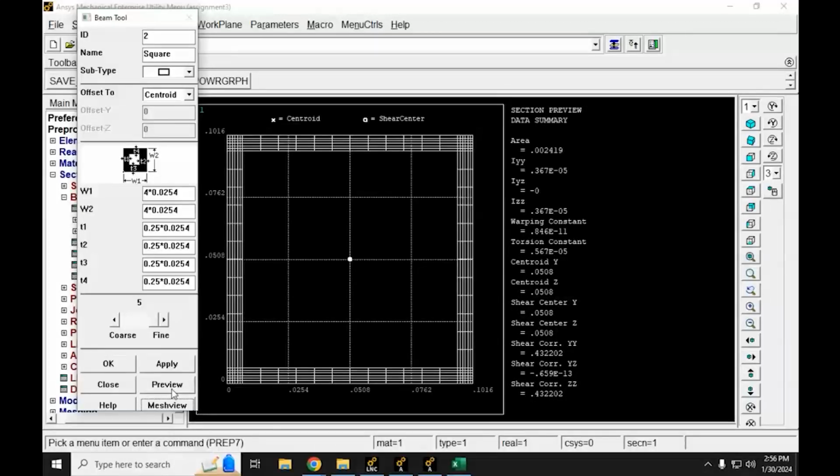The fineness of this mesh really doesn't matter. But if you ever had a scenario where you go past the yield point and start to plastically deform the object, you can figure out where the yield surface is. It's going to yield first at the outermost fibers, so it'll yield most at the outermost fibers, and then the yield surface is going to go down. You can figure out where that is if you put enough mesh cells in the cross section. We're not doing anything that complicated, but it's possible to do that in software.